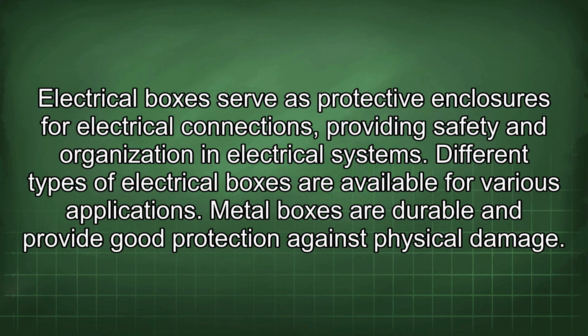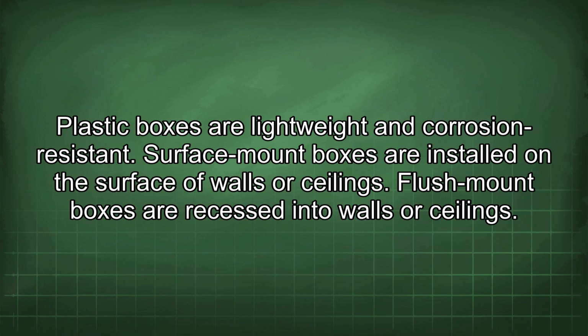Electrical boxes serve as protective enclosures for electrical connections, providing safety and organization in electrical systems. Different types of electrical boxes are available for various applications. Metal boxes are durable and provide good protection against physical damage. Plastic boxes are lightweight and corrosion resistant. Surface mount boxes are installed on the surface of walls or ceilings.